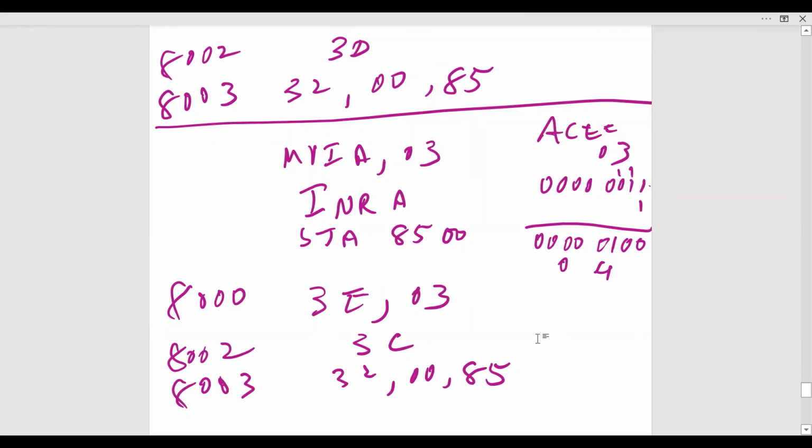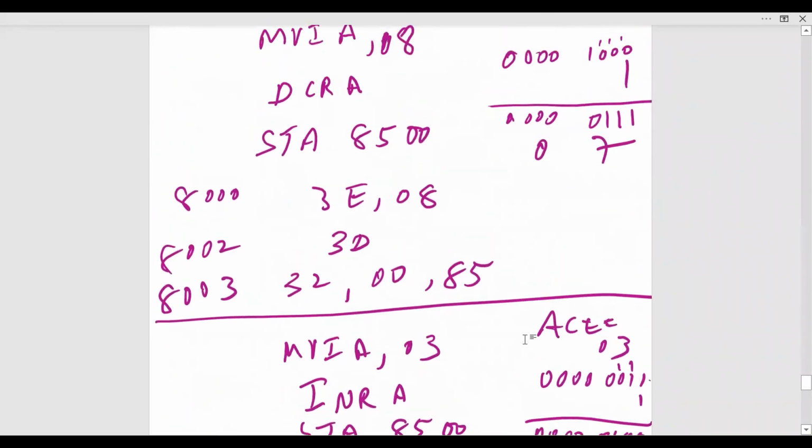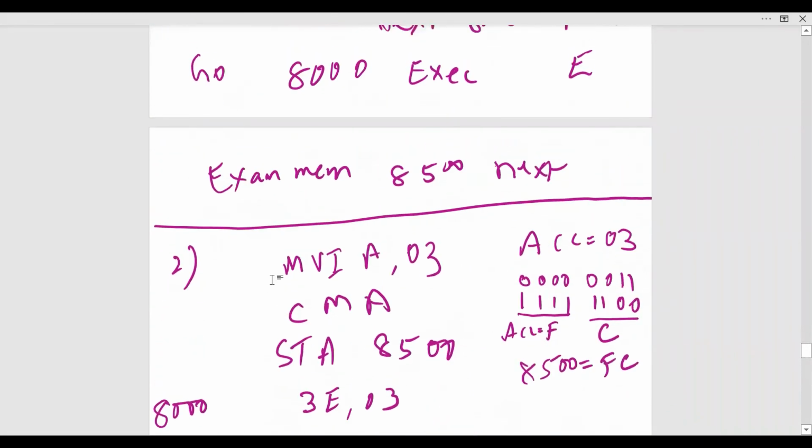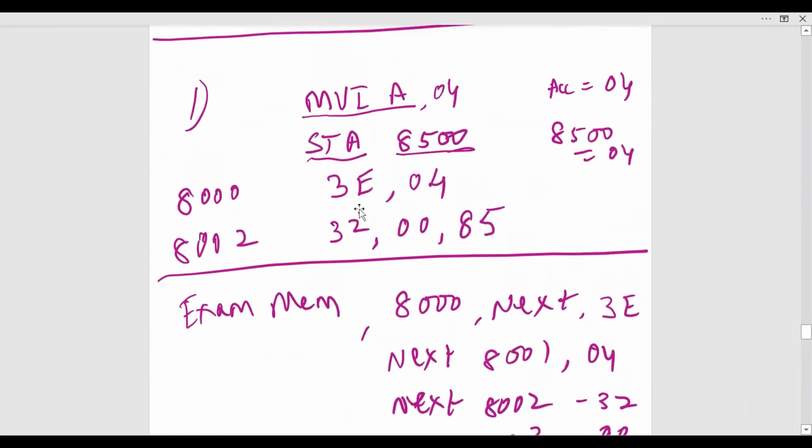So these are the simple assembly language programs in 8085. I have shown programming with 3 different types of instructions in 8085, that is single byte, 2-byte, and 3-byte instructions. Here I have used only the 2-byte and 3-byte instructions. A 2-byte instruction consists of code and operand. Code for MVI is 3E and operand, that is data, is 04. And a 3-byte instruction consists of code as well as the address of the memory location where the data is or where the data has to be placed.